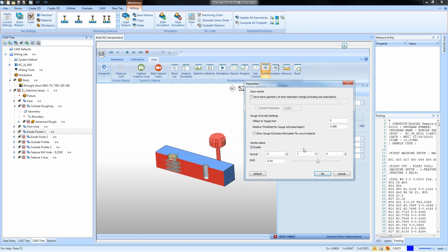You can adjust which axis it's being referenced on. Right now this is going in Y, so I could make this 1, and then I could make this 0, and now it will cut from that direction in order for me to be able to cut away the part. I think I can make this a negative, and then it switches which side it works from, right? So this is so you can get some cutaway views. I don't know if you can do 2 at the same time. Yeah, I guess you can.